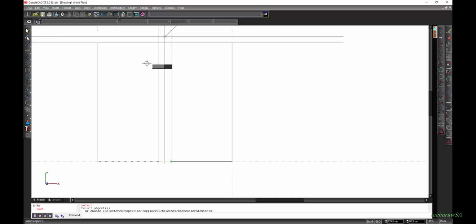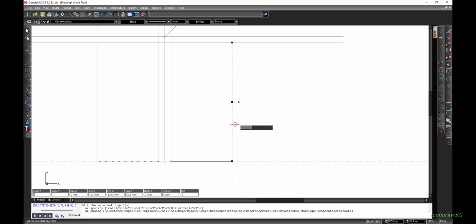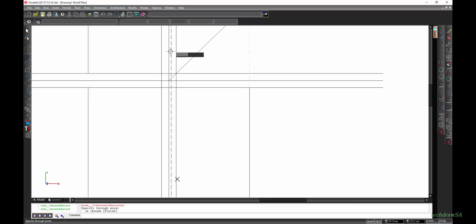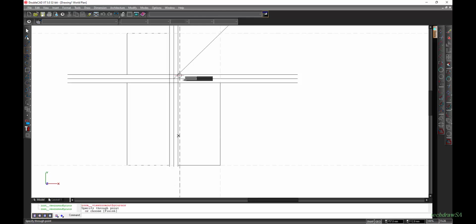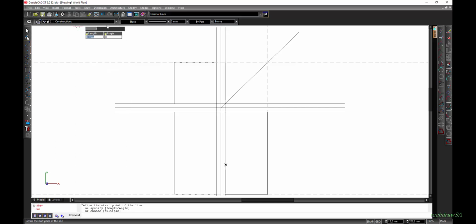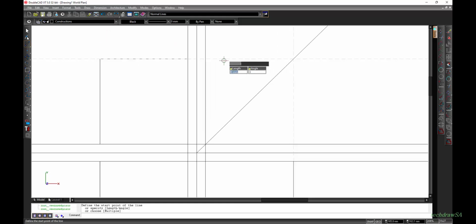And then if you use your selector tool, you will see that your right view has single lines, not one complete box like we did in the previous view. And here you can then select, and if I want to create the grid lines or the margin lines, if there weren't any, I could have done it now with my construction line. And now I just want to draw construction lines on the 45-degree mirror line. So I'm making sure that I'm drawing on the constructions layer.